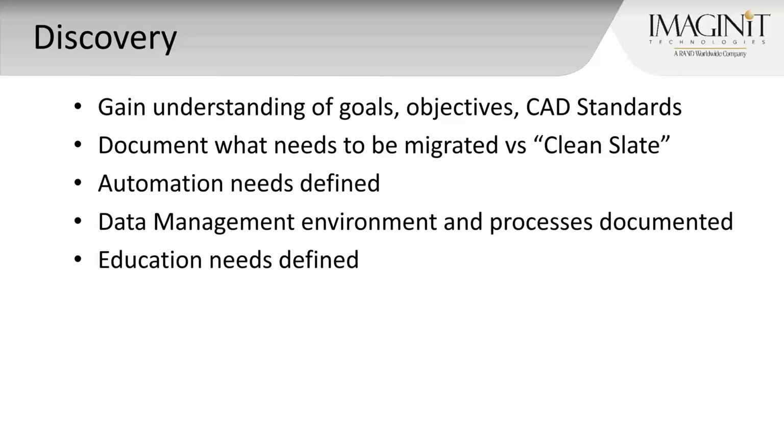Any automation absolutely needs to be defined from the beginning. So we typically will tackle the automation first to make sure that those utilities will work in the Autodesk environment. And we may translate a handful of DGNs to DWGs that are necessary for macro utilities and things of that nature, so that we know that the programming is ready for the translation of the files.